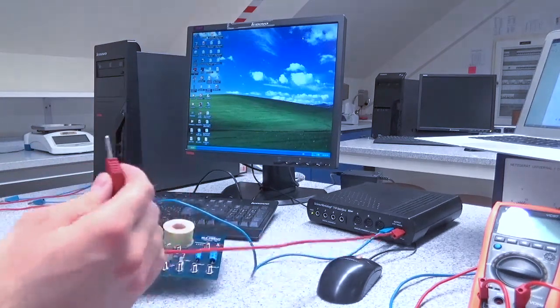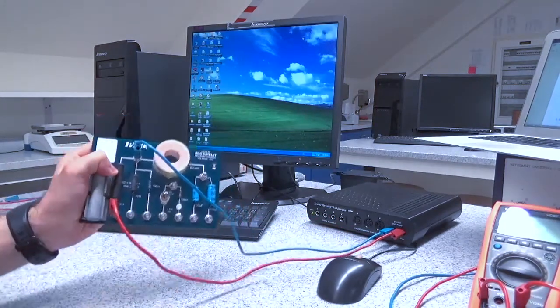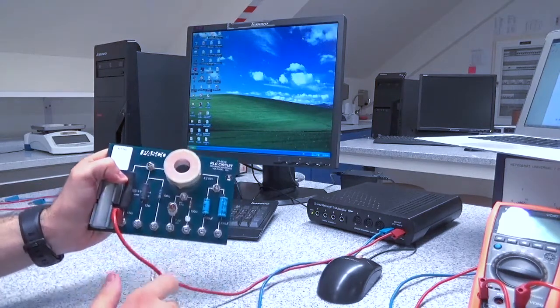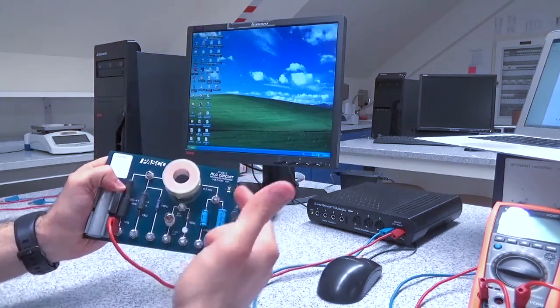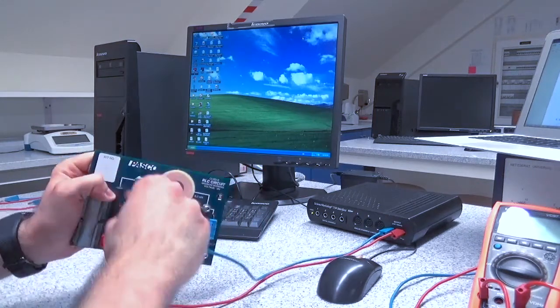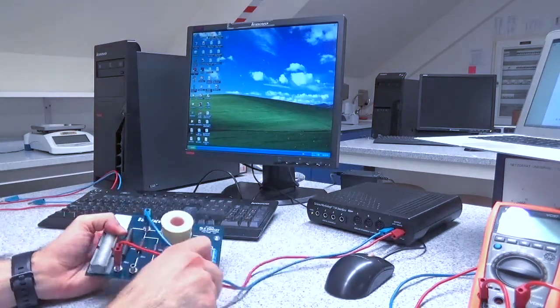So we are going to bring one connection from one output and plug it into that 10 ohm resistor, and then over here we have a common terminal in that circuit board. That terminal is basically a common terminal from which we are going to take out an electrical wire and branch it into the ground terminal over there.